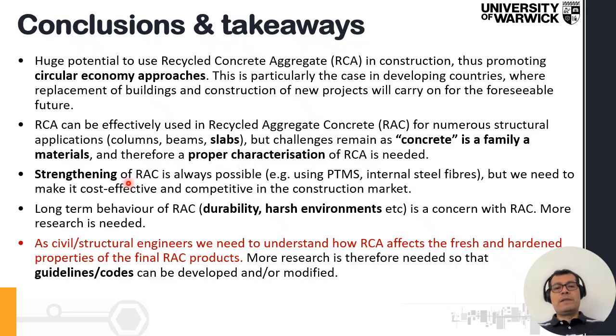We can always strengthen recycled aggregate concrete. We can use the metal straps. We also did some work with internal steel fibers, but obviously we have to keep in mind that that may actually increase the cost of the concrete. And when it comes to construction, cost effectiveness is one of the main things to keep in mind.